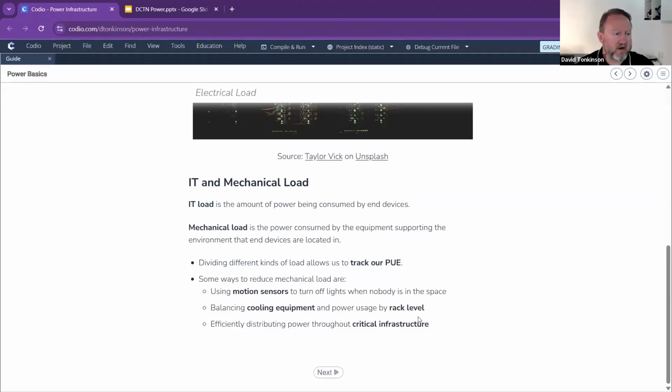Keep those coming. If we're building a data center from scratch, how can we accurately determine or forecast the expected power load requirement? Okay, because if you're building it from scratch, you are likely to know the air conditioning requirements for that building. The reason I say you're likely to know that is because you work on averages.